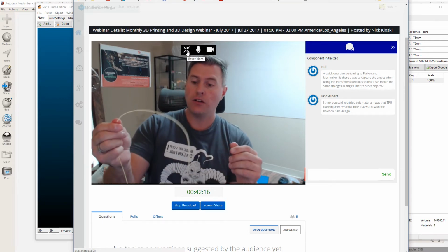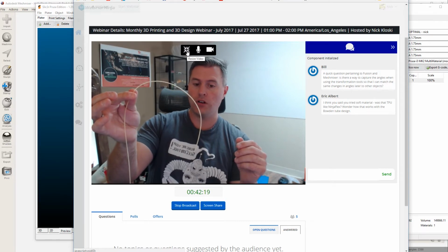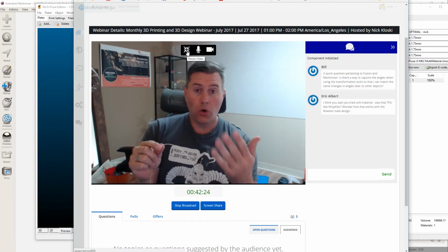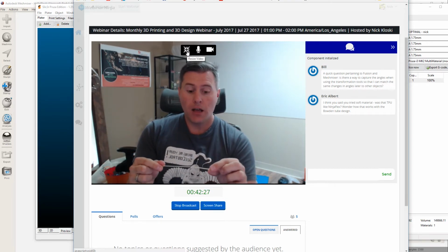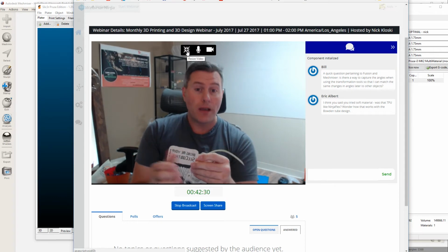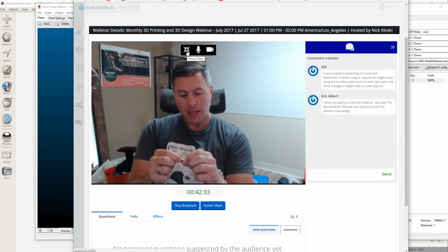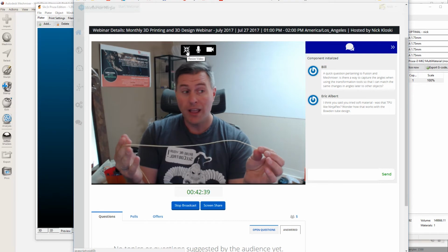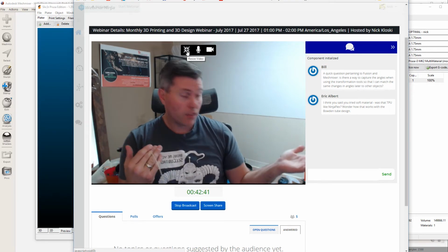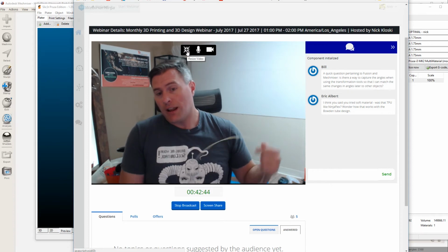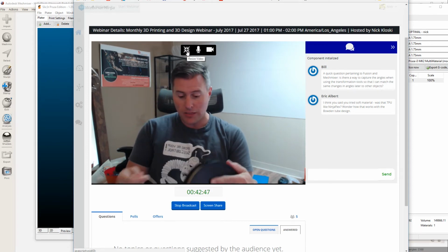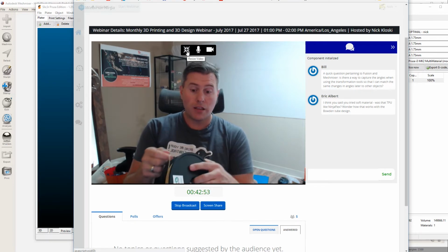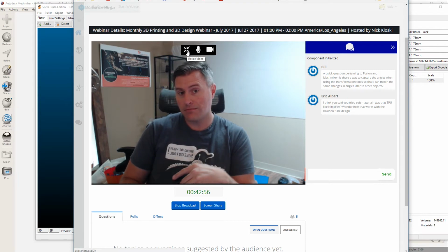Although, with that said, this kind of does fall even on its own a little bit, and I did not slow down at all when printing with this. I slowed down the whole print to about 50 millimeters per second, but I didn't slow down any more for this. Don't know about NinjaFlex, and I don't know what the Shore hardness is on this, but this is PVA, so this is essentially a type of white glue, and it worked just fine at 50 millimeters per second with these Bowden tubes. Don't know if that answers your question, but it is pretty good, and this certainly is softer than the Maker Geeks flexible material that I also successfully printed with, if that helps.